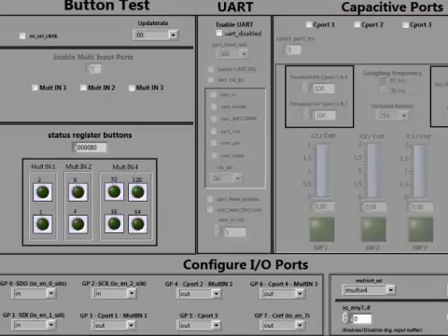As you can already see here, the pins 3, 4 and 6 are labeled as multi-in 1, 2 and 3. This means that you can connect multi-input keys using resistors on these 3 pins. Please refer to the PS09 datasheet for how to exactly connect the keys. We call each of these pins a multi-input port. On each multi-input port you can connect up to a maximum of 8 keys. Thus for 3 multi-input ports you can connect up to 24 keys.